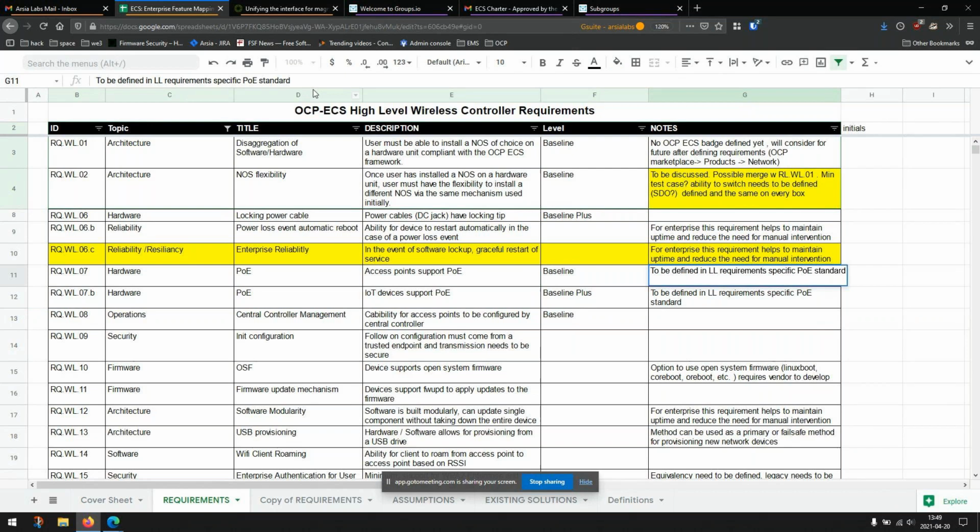So just maybe some commentary on the enterprise side. The majority of deployments are based on PoE. People don't want to buy all the power bricks to power the access points, and it gives them the ability to remote power cycle. If you shut down the port on the switch, you power cycle the access point. There's a lot of subtlety to it, like the PoE power envelope, which keeps going up as you go to newer generations of Wi-Fi and 8x8 radios, so it's PoE++ in most cases. And 802.11bt is starting to emerge within the enterprise because of the high wattage usage for these higher power radios. So the power envelope is always an issue.